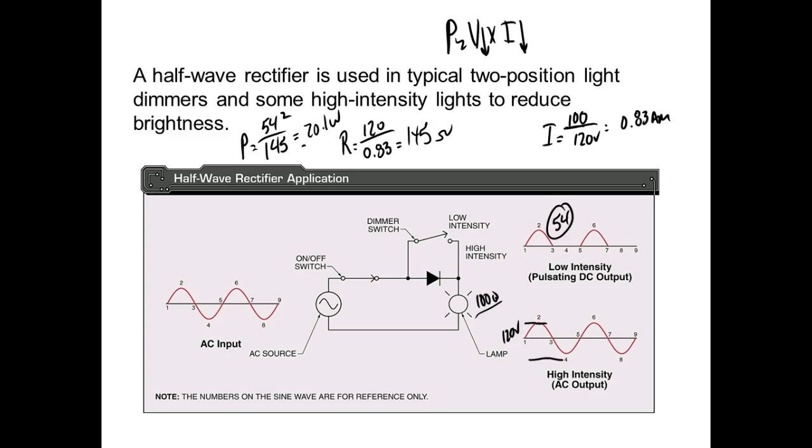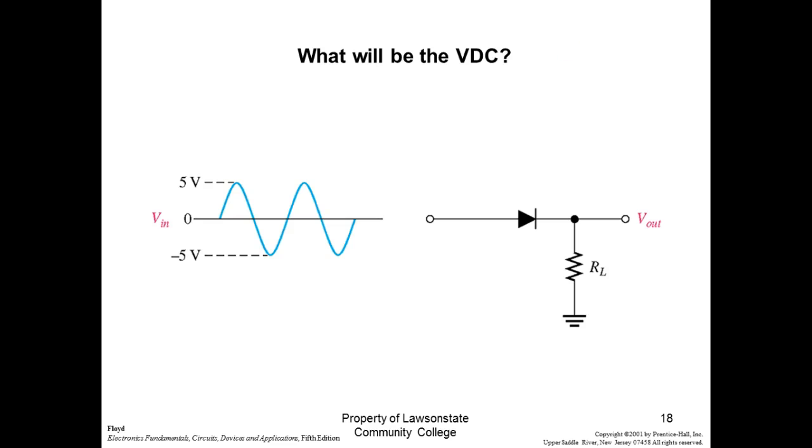So once I set a voltage to the load, the current flow in the circuit is determined by the voltage in the circuit and the load. But what we're trying to say is, how do I get that voltage there? On transformers, if I'm trying to get 100 watts of power at 120 volts, but I use a transformer that goes from 1,000 volts down to 120 volts, 1,000 volts is going to be a lot less current in the source, right? You understand? But what sets the current in a circuit is the load and the voltage you put that load on.